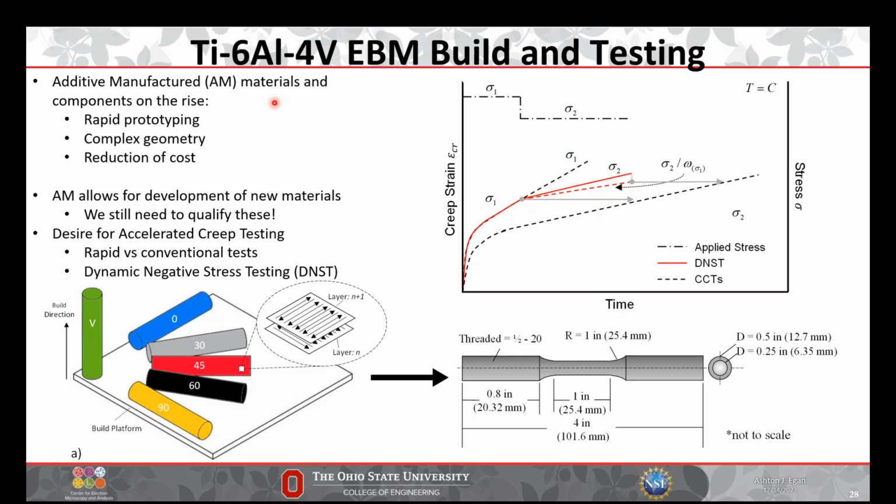So this is actually practical and being used out in planes. And then reduction of costs and reduction of waste material, right? So if you can build your part to near net shape, you don't have to worry about all of this machining loss and basically the value added problem where you're paying a guy to sit there and machine this for an hour or something, right? So it can be a lot more cost effective as well.